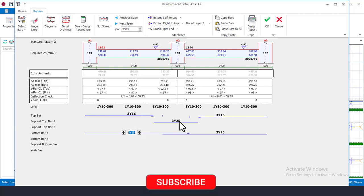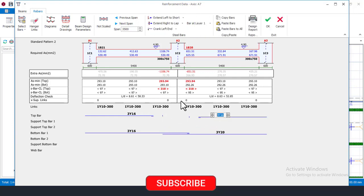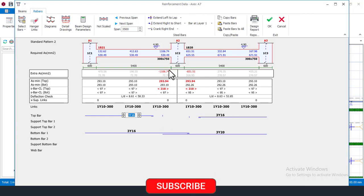So I'll have to convert this 25 diameter to what? To at least Y16 or 20 if I can do that. So right now I'll have to do what? Reduce this first to what? To reduce this now entirely and remove it. Let me just take this off first entirely. Now I said there is not a failure, so I will have to extend this my reinforcement into the column or the support here and also into the support here. So right now I will have to come here, click on this first, right click here and extend this into what? Into the column.